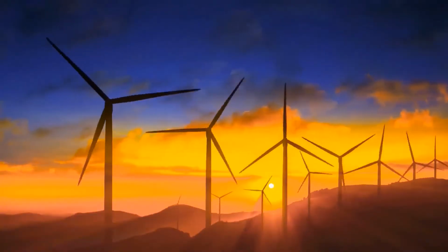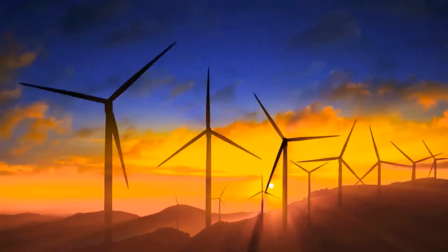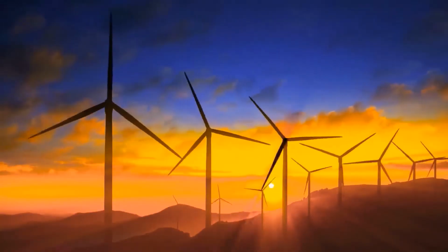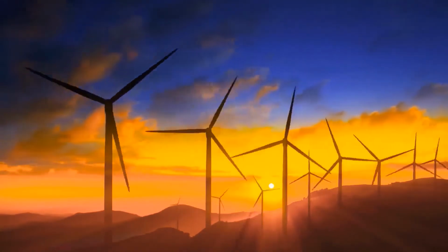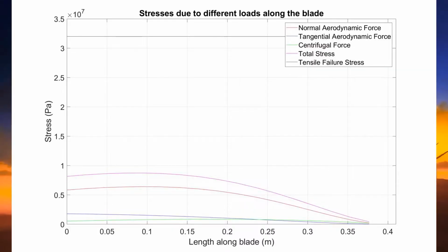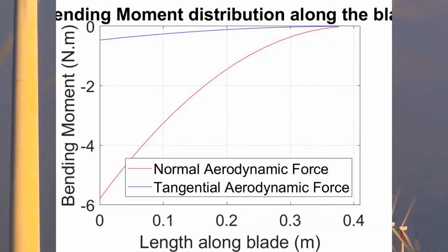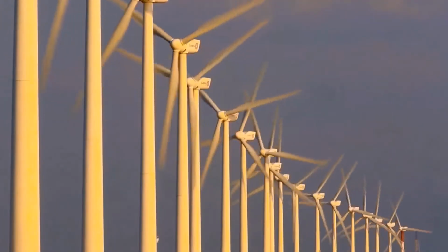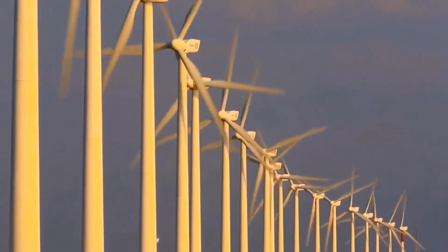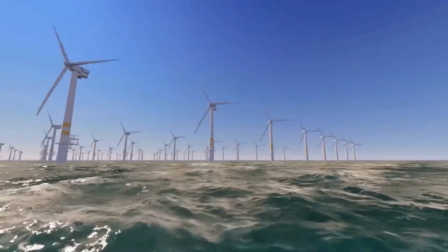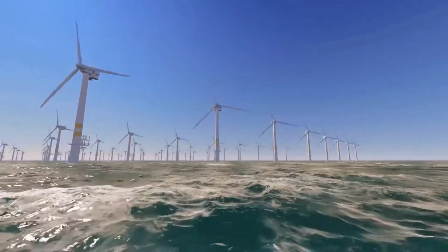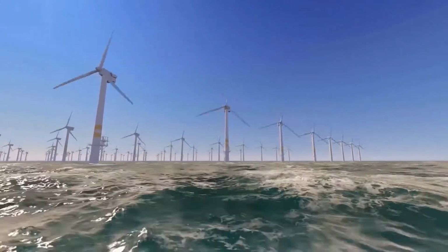The most distinctive part of our turbine blade were its thick cylindrical roots. We forgo any aerodynamical advantage we could get from this part of the turbine blade, and this served a purely structural purpose. As we can see from our 2 graphs, stresses and bending moment are highest along the root tip, and that's why we chose the cylindrical shape. Using simple beam theory, we calculated our blade deflection along the length of our blade. Our thick cylindrical root increased the stiffness of our blade and deflection was minimized.